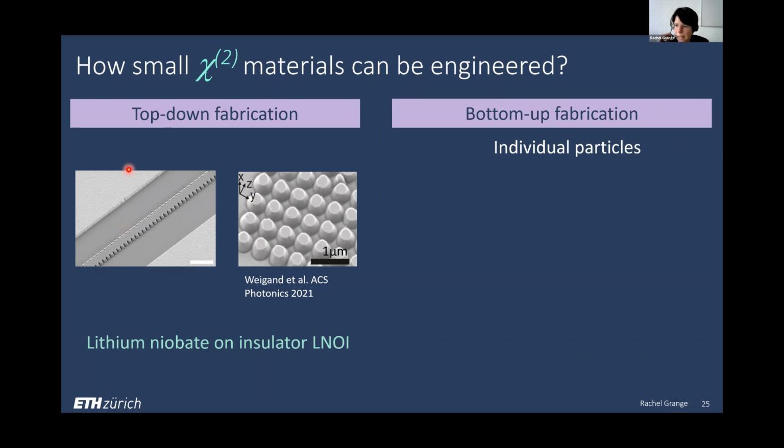Did we try to balance between physical and chemical etching to gain more straight walls for lithium niobate metasurfaces? Yeah, so I didn't cite it here. We just have a paper out in the Nanophotonics journal on ICP etching, and actually how we have to do some chemical etching as well, or let's say wet etching as well, because when we do the ion etching, argon ion bombardment, you have redeposition of amorphous lithium niobate on the walls.